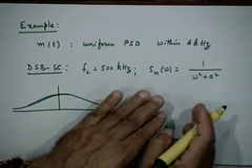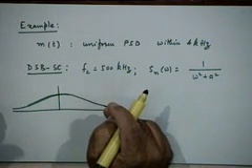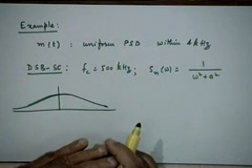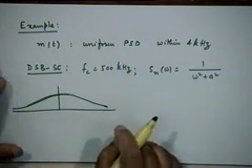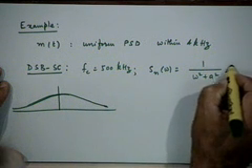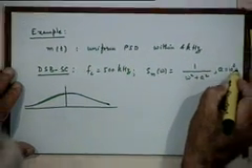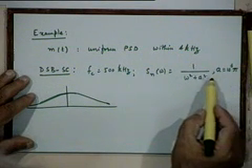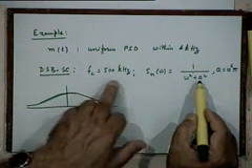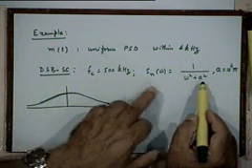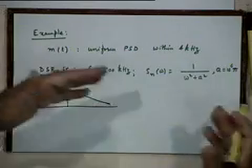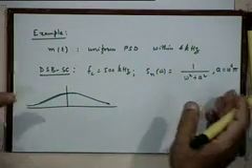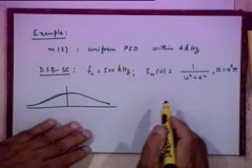Which is what will happen if white noise were to be first passed through a filter with this transfer function, right? So it's some kind of filtered noise. It doesn't matter, just for the sake of argument, and the value of a is 10 to the power 6 pi, just some numerical values to give you some feel. And this makes sense because if your carrier frequency is 500 kilohertz, it is noise up to about that bandwidth which is really going to play a role, if at all.